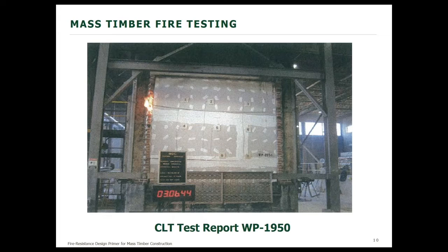The test specimen in the E119 test, for which we have the picture here, had a half-lap joint right in the middle of the panel. Even though we were hoping for a 2-hour fire resistive rating when we started, the test lasted for 3 hours and 6 minutes, and the failure was due to the flame through endpoint criteria. You can see on the left-hand side of the picture, the flame through. The CLT panel was still carrying the 87 kip load at this point in time.